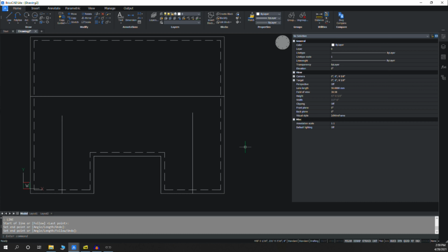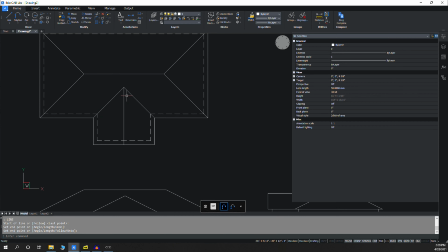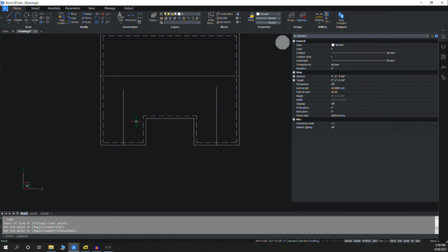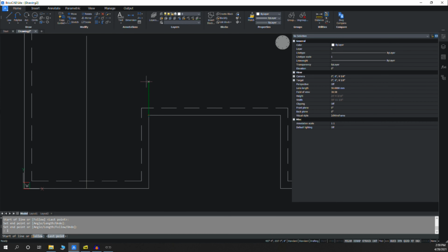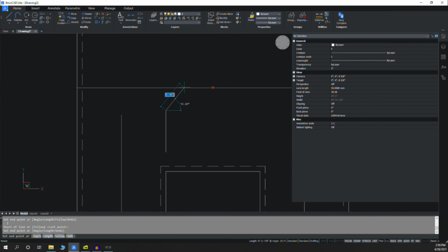Okay, so now here is the confusing part. If you remember when we drew this roof over here, we just assumed that this valley was at a 45-degree angle. That doesn't work when you have a 6/12 pitch intersecting with an 8/12 pitch. What you ultimately have to do, and I always forget which direction it's supposed to go, is make one line 8 foot, because this is the 8/12 pitch. And I'm pretty sure that the line is just perpendicular to the ridge line. So you go up 8 foot, and instead of going over 12 foot, I go over 6 foot because the ridge line it's intersecting with is a 6/12 pitch.